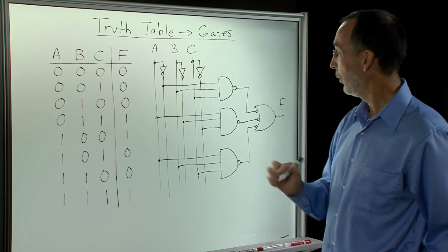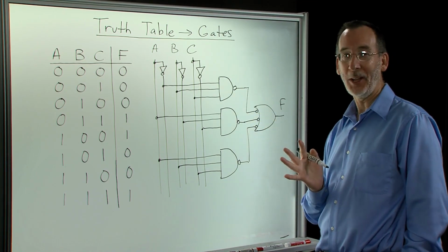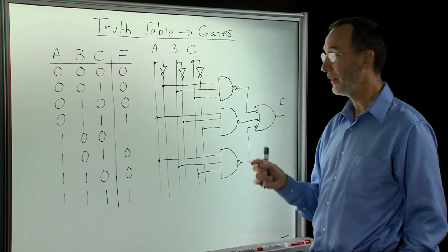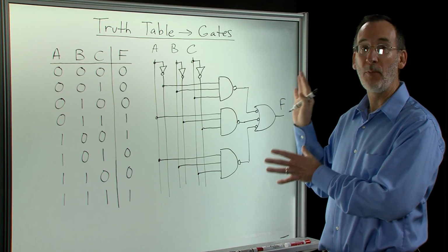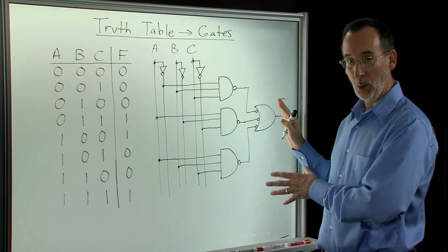Well, why does this work? I hope you see that these bubbles cancel out. It's like they're not there, because I'm going to invert this output, and I'm going to invert it again. So this is exactly the same function as having the ANDs and the OR.